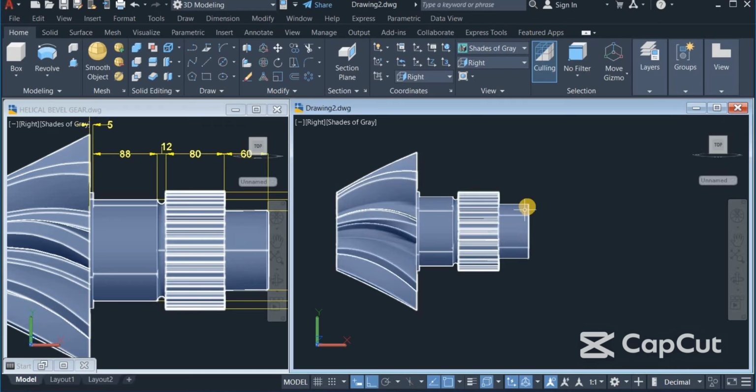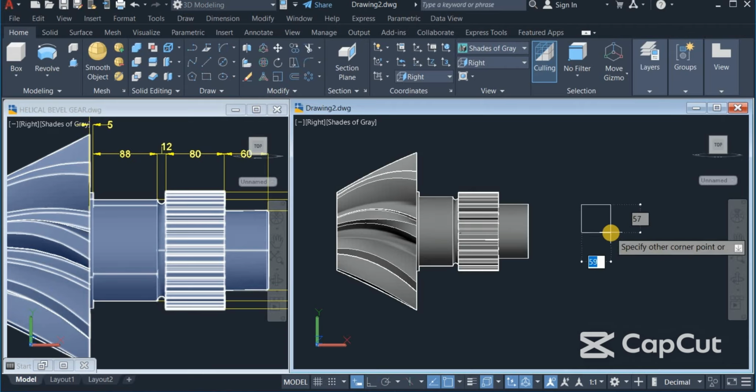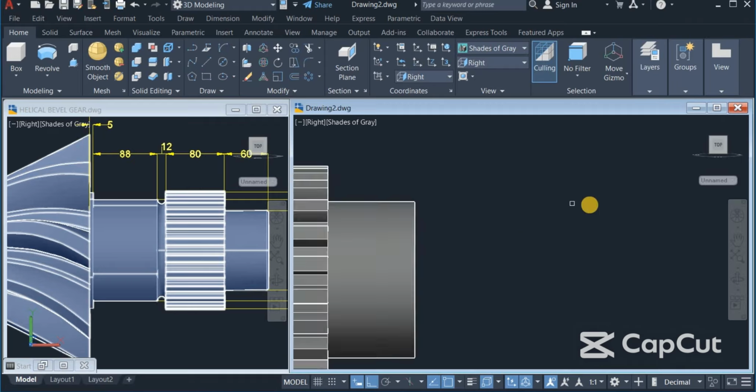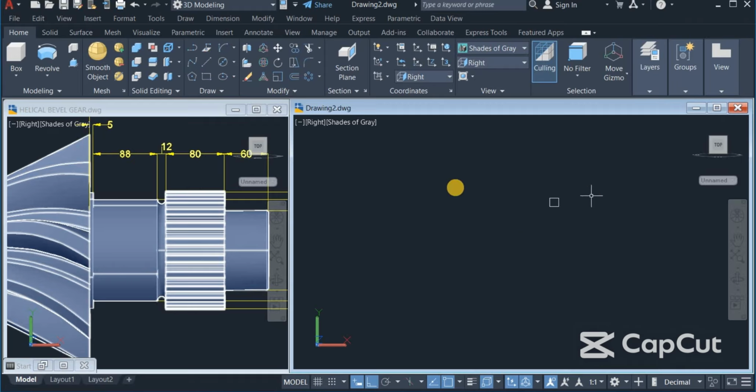So now I'll have to chamfer this portion. So click on the rectangle command. Draw a square of 3 by 3. Enter. Click on the line command and split it. Then trim up this portion. Enter. And join it up. Modify. Click on join command. Alright.